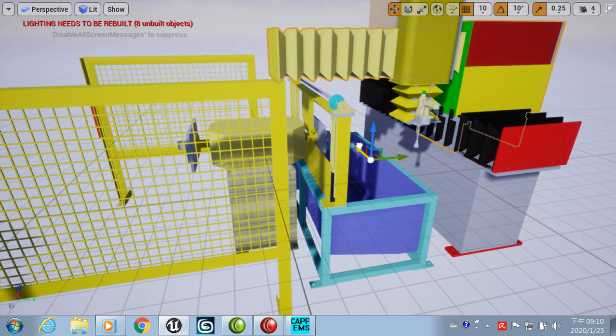Okay, but for the rotating, we have to set the pivot points. The A component, B component follow the parent, the C component. The C component is the child of the foundation. So the pivot point has to be set. How to set the pivot point?